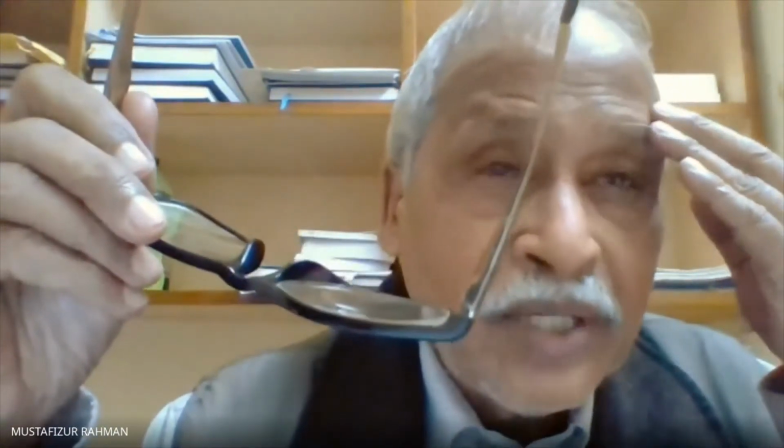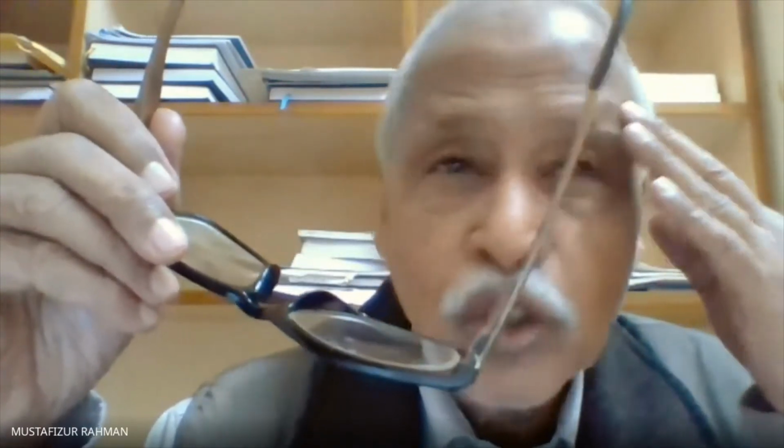So one-way slab means it is having support on two opposite edges, normally the two longer edges. If this slab is supported on all four edges, in that case also a slab may be a one-way slab. The condition is if the longer length to shorter length ratio is greater than 2.